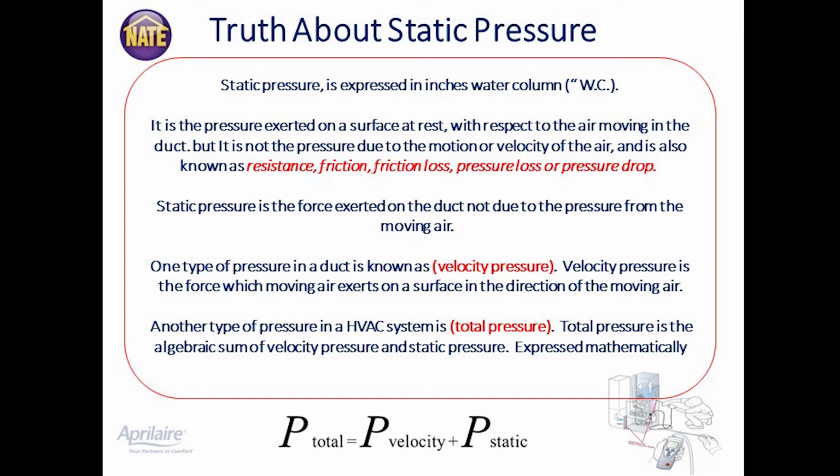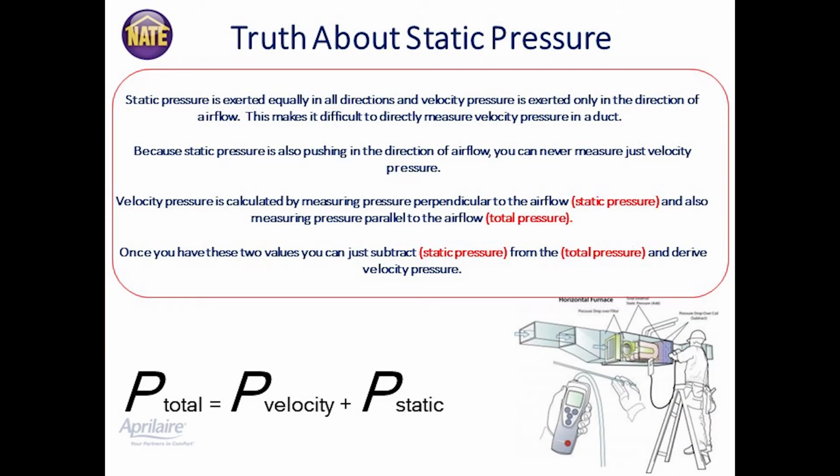But another important factor is the resistance created by that filter material, that media. That frictional loss or that resistance to airflow is what we call static pressure. And that's simply another thing, in addition to the ductwork and the way the duct's designed and the elbows and the branches and everything else, that increases the resistance to the blower being able to move the amount of air it needs to. So air filters are just another component of that static pressure.